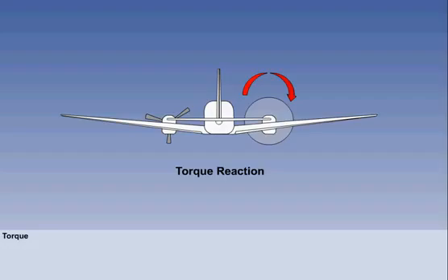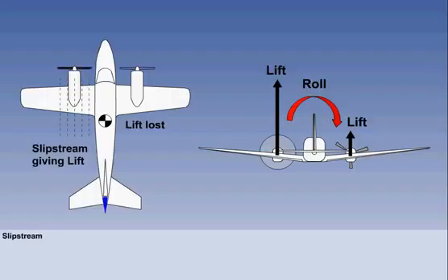As with asymmetric blade effect, this happens only with co-rotating propellers. Note, however, that if the propeller is windmilling, the torque is reversed, but is much less than the torque of the live engine. Any propeller-driven multi-engine aircraft will suffer a loss of lift from the slipstream-induced faster airflow over the wing behind the failed engine. The reduction in total lift will give a tendency to descend, but more importantly, a roll towards the failed engine. The roll is exacerbated if flaps located behind the failed engine and its counterpart on the live side are down, owing to the higher CL.